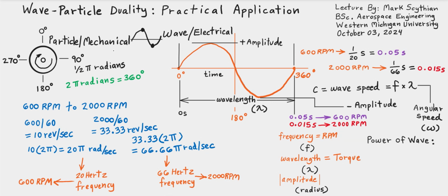So a good practical application is anti-skid vehicle technology. So each one of these wheel speed sensors, they're like 4-channel sensors. They're a wheel speed sensor per wheel. So originally they were kind of like 2-channel, and they transversely pick up wheel speeds. But today we have all this 4-channel independent wheel speed sensing. And so that wheel speed sensor, if you look at the little teeth, there's a little air gap, and that behaves like an AC generator.